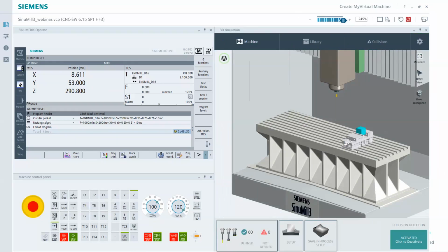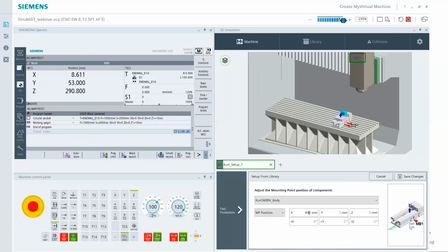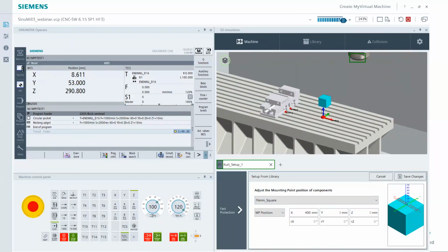So just, you know, 3 items, is it that big a deal? No. But you could have sub-assemblies here that could have a lot of components, and that could save you quite a bit of time. So you use that little MP linking trick, and everything will now move together as one. Now just be careful here, because if you pick the non-linked component, it'll still move like it did before. So you see how I got that independent move?